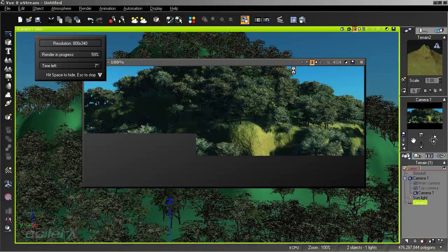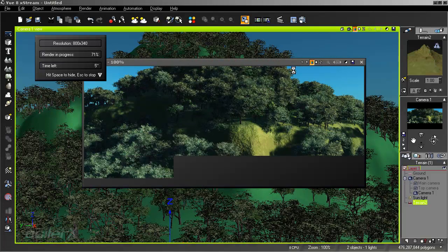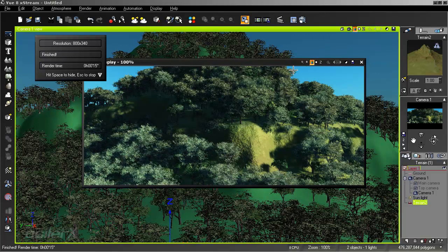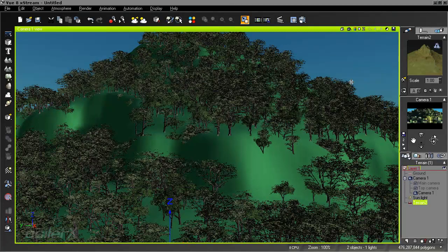If we would just want to have the plum trees on the outside being the smaller trees, either in combination with using the offset or just the fact that they're smaller themselves, so they will automatically kind of block out the edges and fill in that space, what we can do is use a presence control, which is a really powerful way to modify an ecosystem.